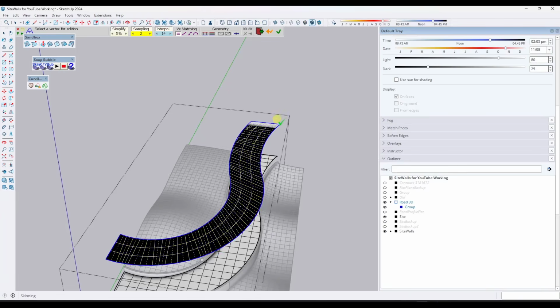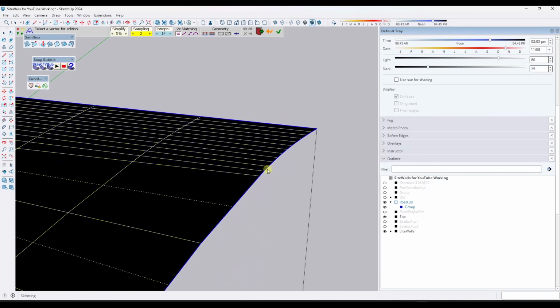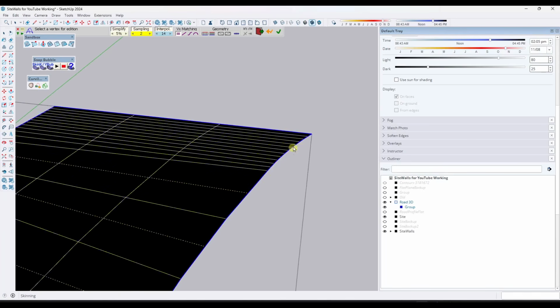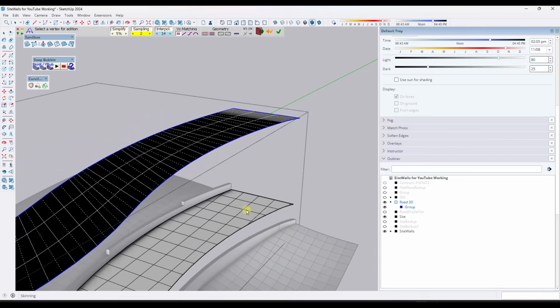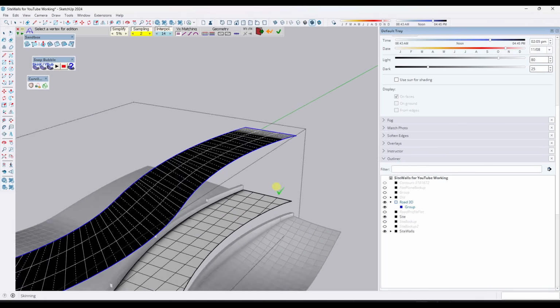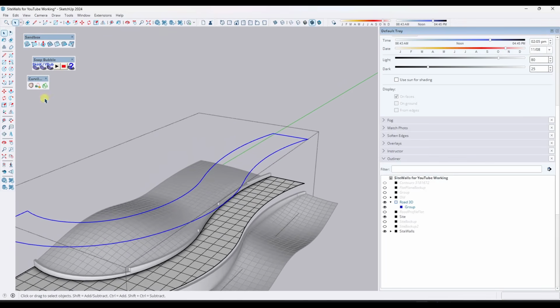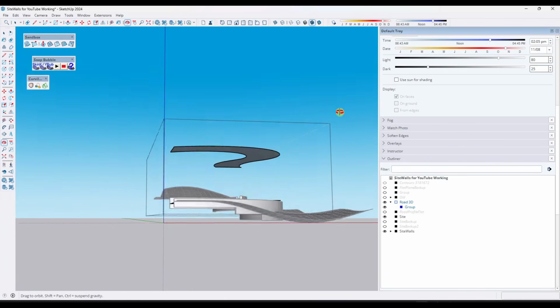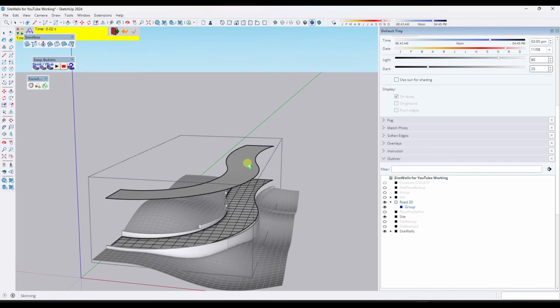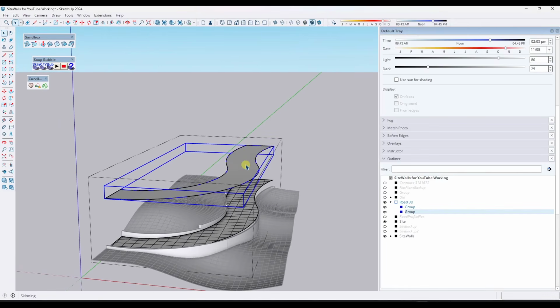Now that can affect your curve, but at the same time, your topology can get a little bit better. So you could select these two edges and even out the number of edges in here. Notice that you don't get this issue with Soapskin in the same way. So you can use Curveloft to create a skin in here, and a lot of times it makes sense, but I think I like the topology that's created by Soapskin and Bubble better.